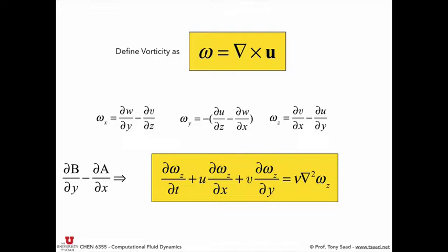So it's transporting vorticity. It looks like every other equation we looked at, specifically the advection diffusion equation. It has a transient term. It has an advection term with u and v velocities multiplying. And it has a diffusion term, so advection diffusion. The only difference between what we did previously and what we're going to do now is that the advection term is nonlinear, because u and v are a function of the vorticity. What we did last week, u and v were constants, right? But the difference is going to be a major difference, okay? We just substitute the values of u and v.